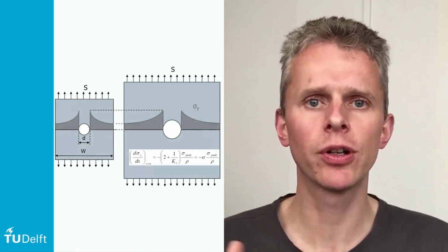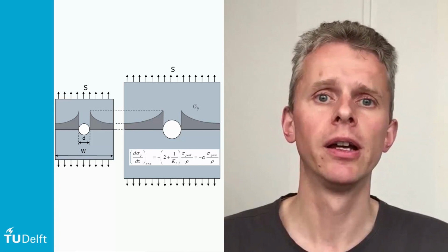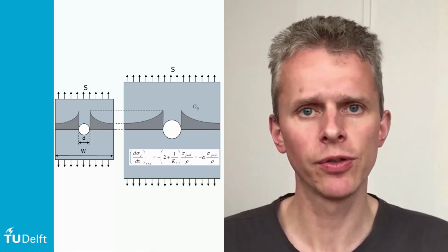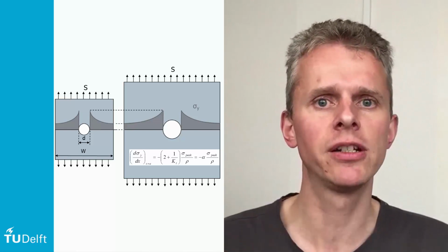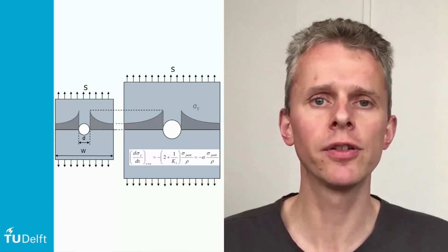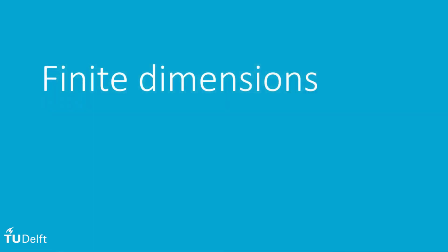We should realize that the stress concentration factor does not capture all the aspects related to the geometry. We may have two different cases, for example two circular notches with different diameters in plates with a different width, that in the end have the same stress concentration factor. But simply because the size of the high stress region in the notch is different, the fatigue performance may still be different. So how do we cope with that in practice? Well, let's have a look at that.